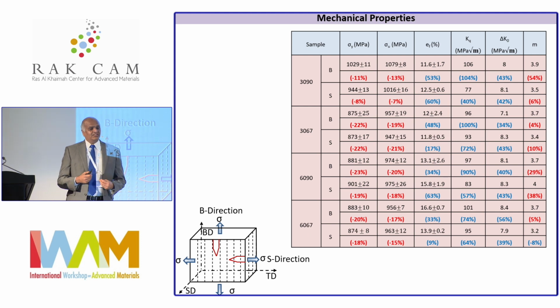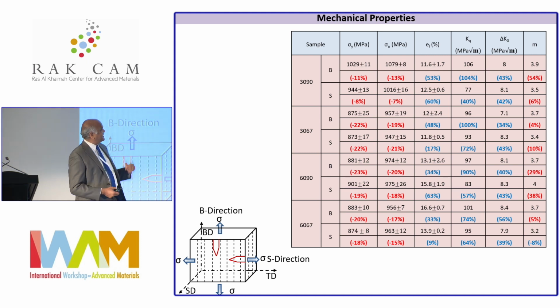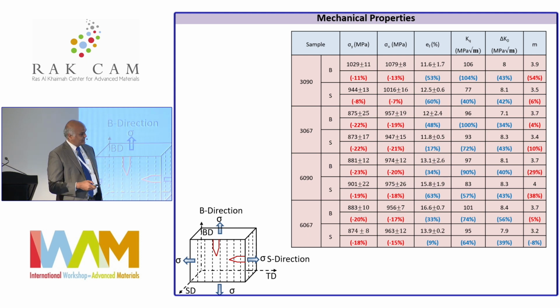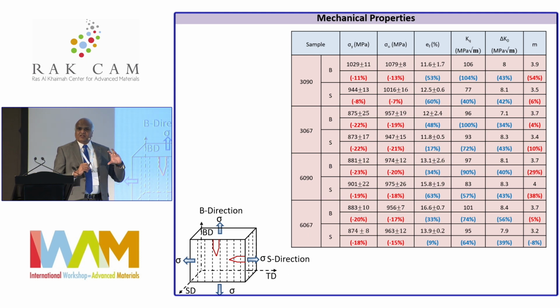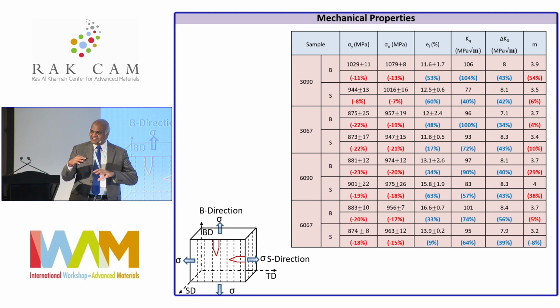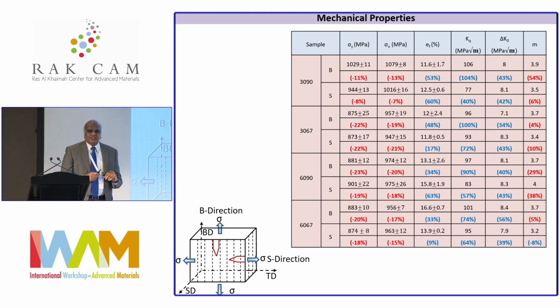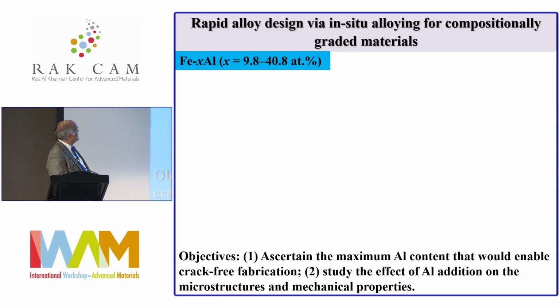Right? So this is the heat and beat. We didn't quite beat here, but the heat, the technology we used, enhanced the strength. And there are also the crack growth properties under cyclic loading, how these things move. So one is by playing around with the processing combinations, layer thickness and scan rotation, I could get different kinds of structures. And then I can also use heat treatment to enhance the properties. So this is the kind of thing that you can do for microstructural manipulation of these alloys, right?